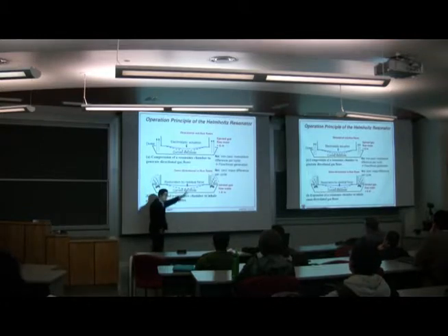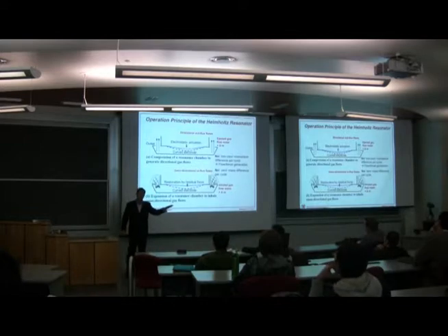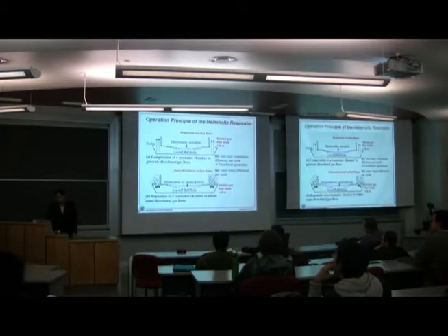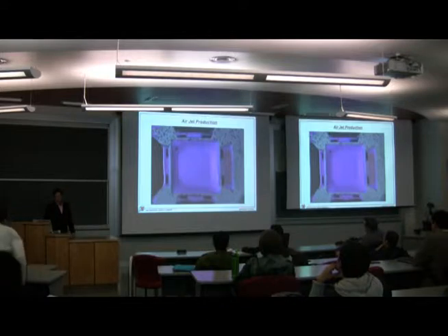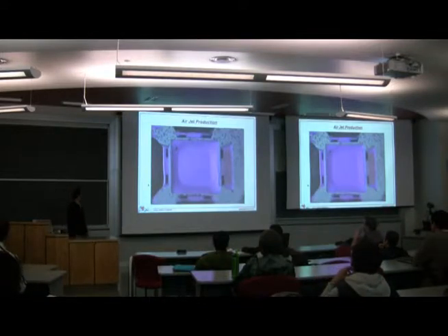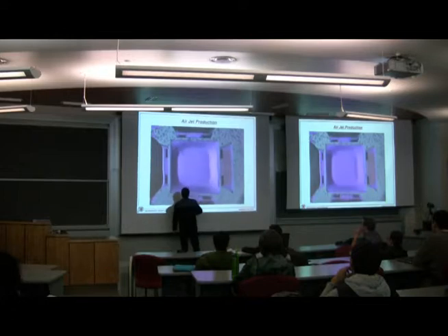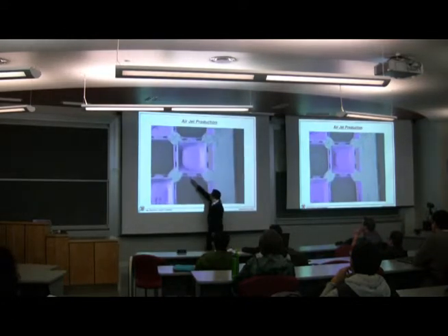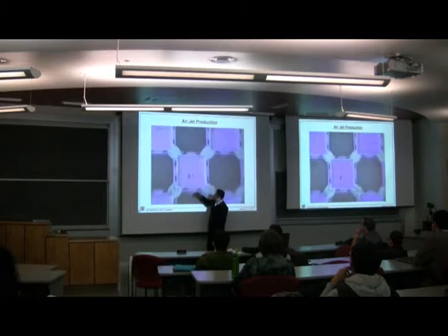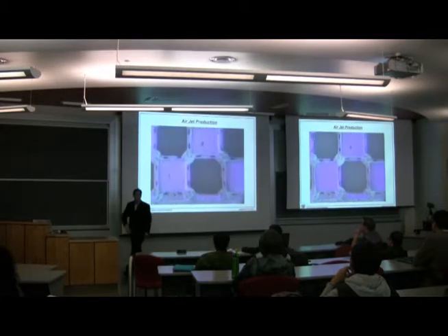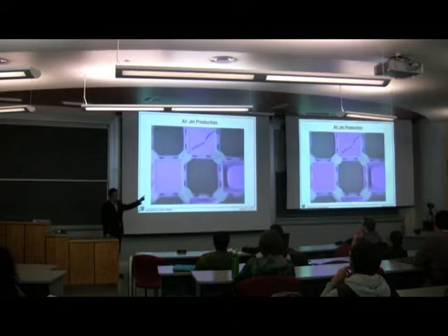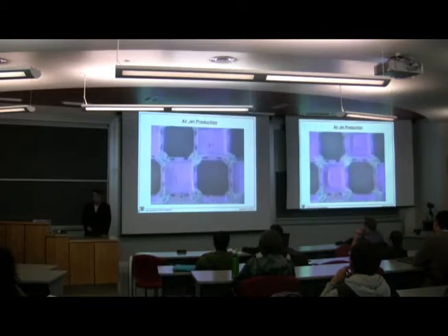So if we repeat it very fast, probably 70 kilohertz, 70,000 times per second, then maybe we can generate a lot of momentum. So we built this with MEMS. We are very good at microfabrication. And this is the membrane, about 1 millimeter in size. This membrane is vibrating this way, and air is coming in and out around these slots. And of course, this is built at chip scale. So of course the frequency is low, but just to show it.